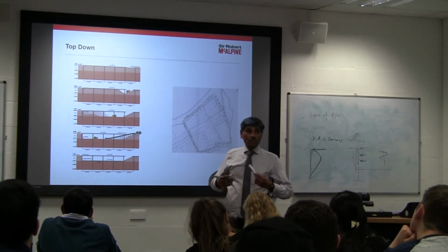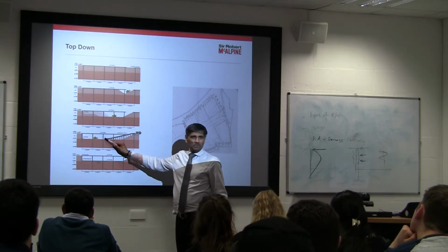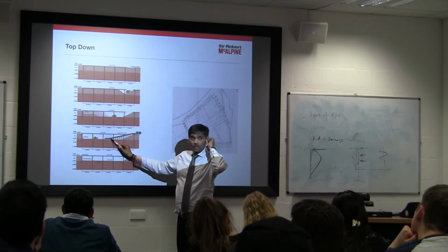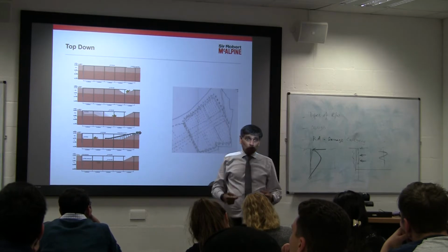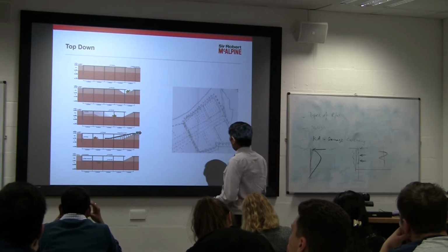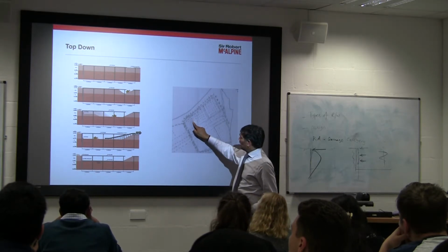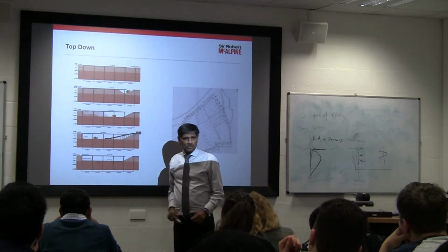Second way of doing it, if you got space, you put a conveyor. Yeah? So the conveyor comes out, so the guys who are digging here, they just dump it to the conveyor and it comes up. Because this is a very large site, there is scope for the conveyor to be used again and again. So we put a big opening here, 8 meter by 8 meter. Through that the conveyor belt goes there, and then you start digging underneath the deck.